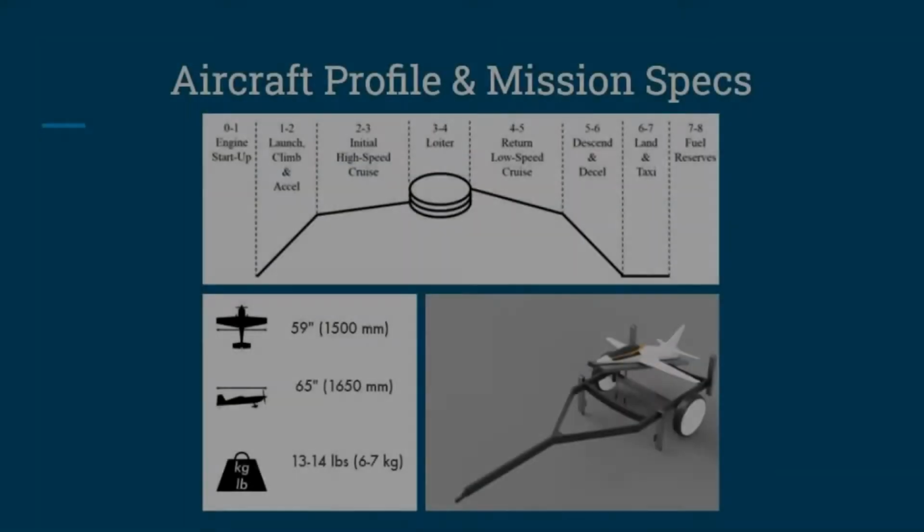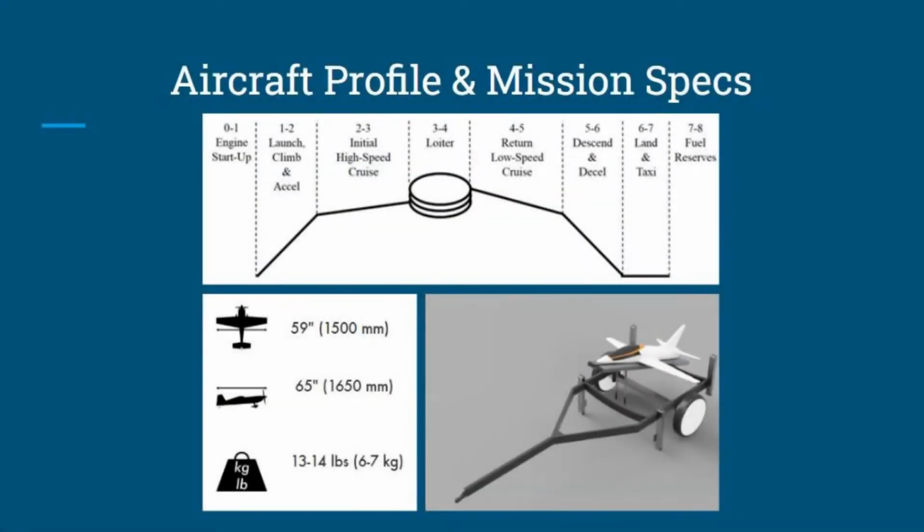We will be discussing the analysis and findings made during this project and will give suggestions to our best design outcomes. The project goal is to design a turbine engine and a radar bracket system that will be integrated onto the Rebel Hot RC Sport Jet. This will enable the aircraft to take off from a launch rail and climb to Mach 0.25 at initial cruise. The aircraft will have a combat radius of 5 nautical miles and will operate at 10,000 feet for the majority of the flight. A big emphasis on the mission profile is to produce a maximized loiter time.